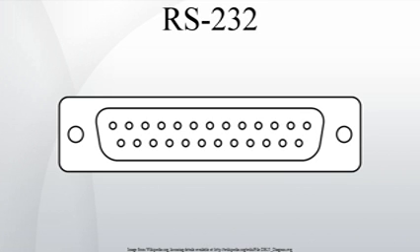3-wire and 5-wire RS-232. A minimal 3-wire RS-232 connection consisting only of transmit data, receive data, and ground, is commonly used when the full facilities of RS-232 are not required. Even a 2-wire connection, data and ground, can be used if the data flow is one-way, for example, a digital postal scale that periodically sends a weight reading, or a GPS receiver that periodically sends position, if no configuration via RS-232 is necessary. When only hardware flow control is required in addition to two-way data, the RTS and CTS lines are added in a 5-wire version.